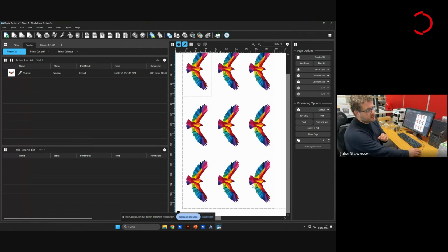And this is definitely our recommended way of cutting, because you get rid of all sorting issues, and it's the fastest way, because first you will cut only a fraction of the length of the cut, and second you will also get the plotter to a higher speed, because the length of the cut is much longer, so the cutter will speed up to a much higher end speed and be able to cut much better. So that was all for now.